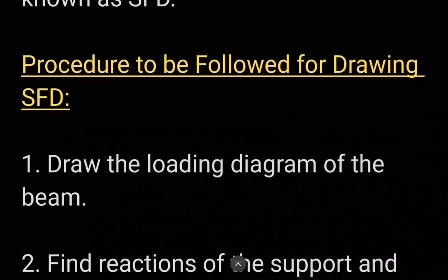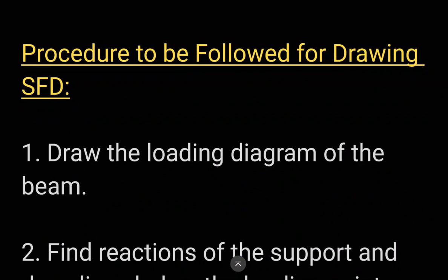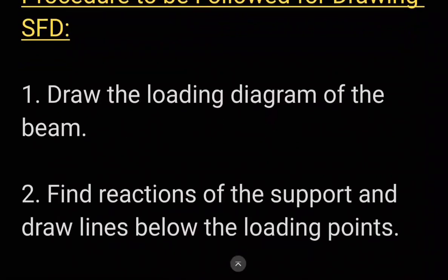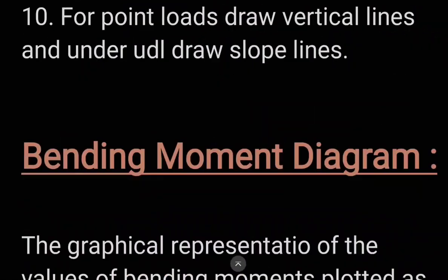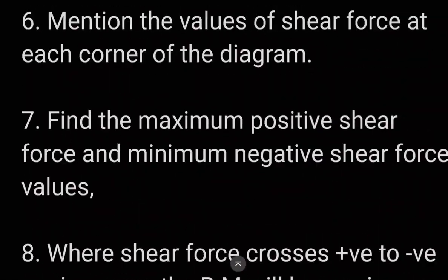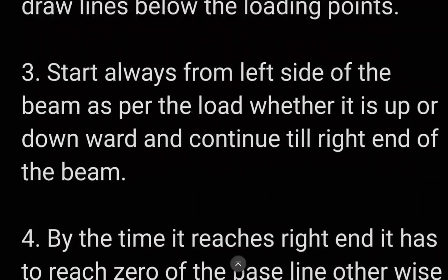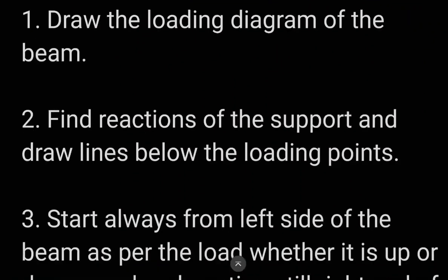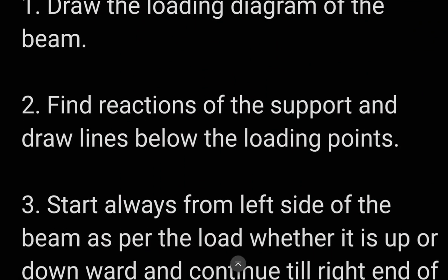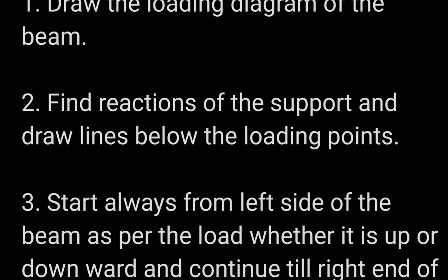Procedure to follow for drawing the shear force diagram. There are 10 points. Number 1. Draw the loading diagram of the beam. Number 2. Find the reactions of the supports and draw a line below the loading points.